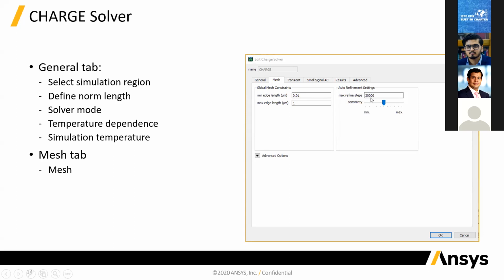This is because if you have a really big simulation and maybe because of some error in the setup or some issue in the solver, it might go into an infinite loop and just blow up your system memory because it's just trying to refine the mesh over and over. So this is a check that it will automatically stop after a certain number of steps.